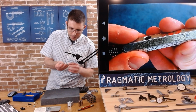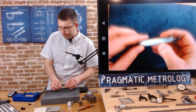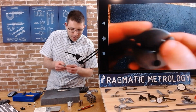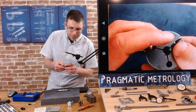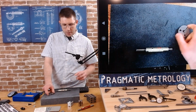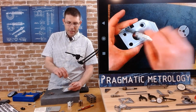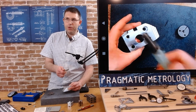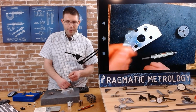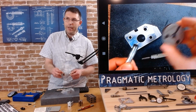Right there, 2B. And a ring gauge is going to say 2A. And that corresponds to our holes. So our hole for a plug gauge is a 2B hole, so we use a 2B gauge. And for an external thread, we have a 2A thread and a 2A gauge.